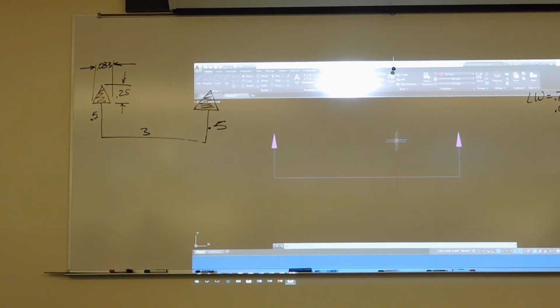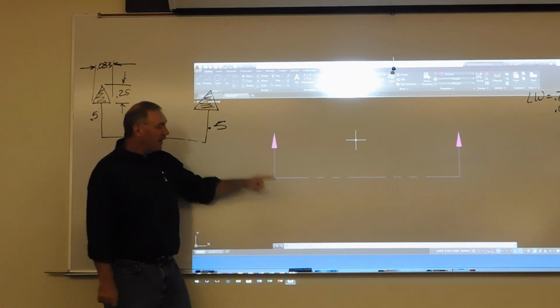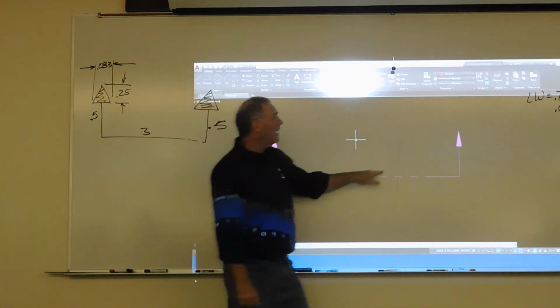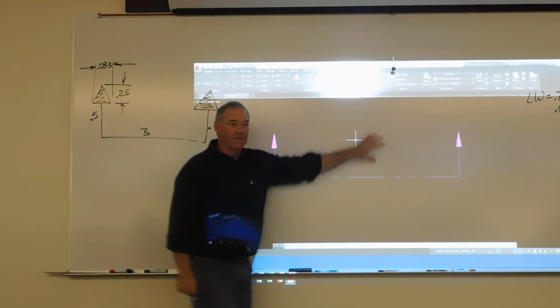But all I'm going to do is grab my line, come up here under line type, and put it to a phantom 2. Okay. Now, due to the properties of this, I can switch this to any layer I wish now, but it's always going to be a phantom line since I switched the individual property of it. So that's one thing you just got to be aware of.